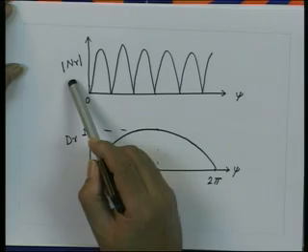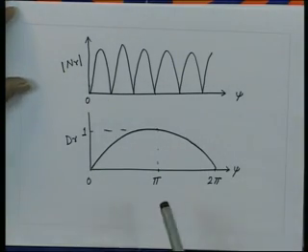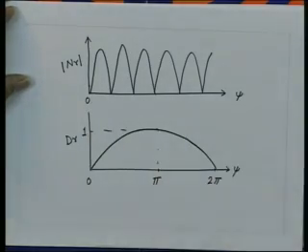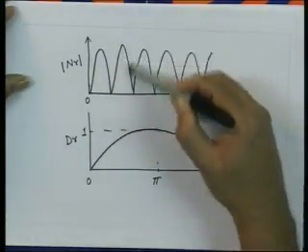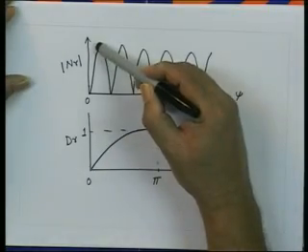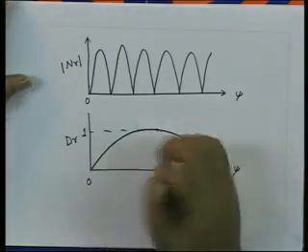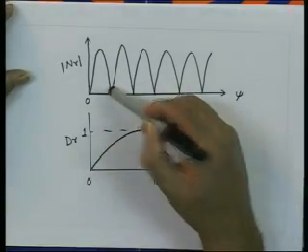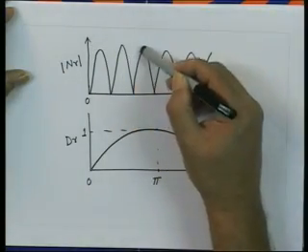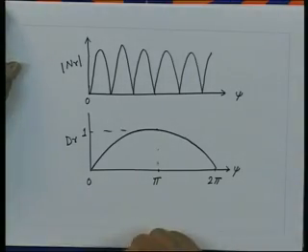So, here we are plotting the numerator modulus of that, and here we are plotting the denominator, and we vary psi from 0 to 2 pi. So, this function is a rapidly varying function if n is large, and wherever this function goes maximum, at that time we have a local maxima. When this function goes to 0, we have a null. So, essentially these directions where this function is maximum correspond to the directions of the side lobes.